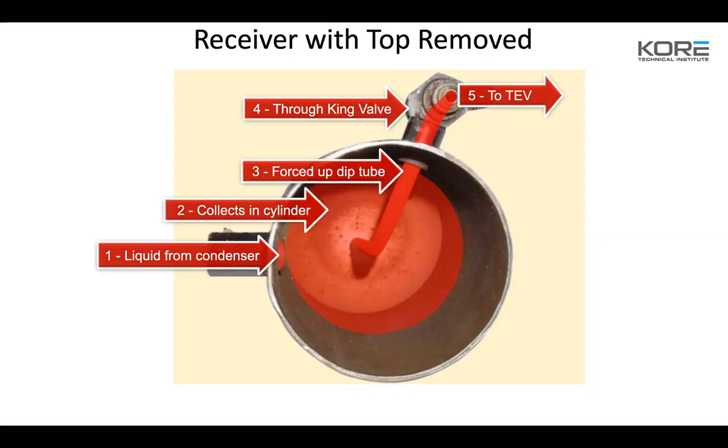Okay. When you guys snap torch the receiver, you see this. If you're looking at it like a clock, you've got your inlet at 9 o'clock, and you've got your outlet between 12 and 1 o'clock. Where I want you guys to snap torch this style receiver is at the 5 or 6 o'clock area, on the opposite side of where the refrigerant's coming in and going out, because you're going to get different readings.